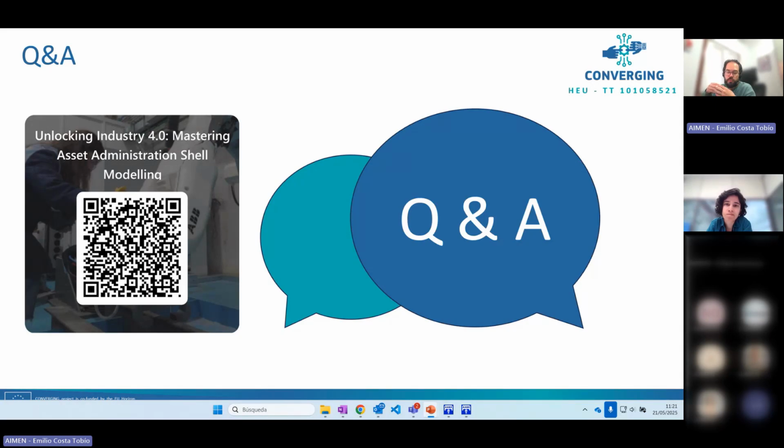So you will need, first of all, an external server, for example an MQTT broker or an OPC UA server, to send the information. And then with the data bridge, you would configure the mapping from this server to each property of the AAS, and in this way you would update the AASs through the data bridge component.